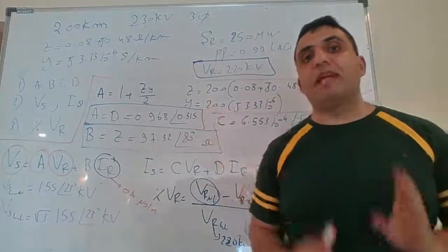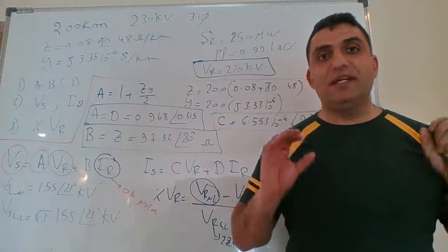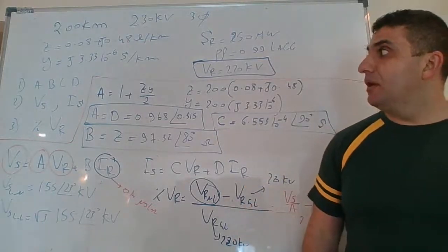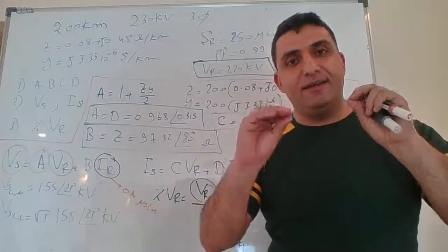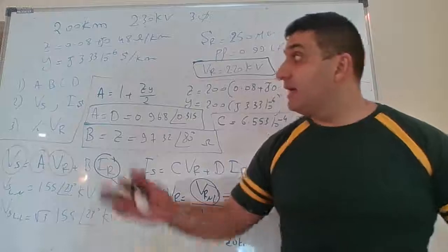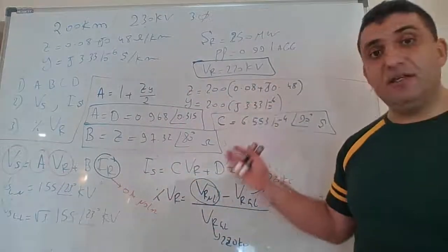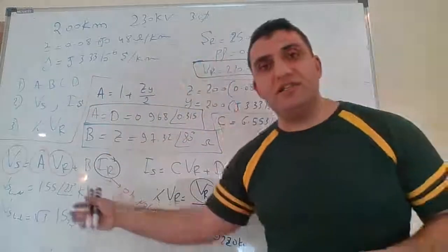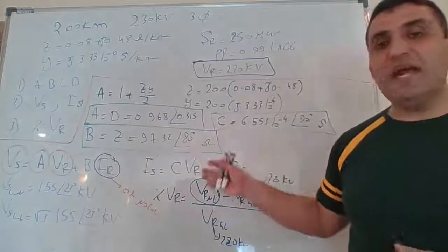So let's recap before we finish this mini session regarding the medium transmission line network. I sketched the circuit of a medium transmission line. I did nodal analysis, normal circuit analysis. I ended up with the ABCD parameters. I found ABCD, and then any question will be very easy to solve. This will give me major advantages.